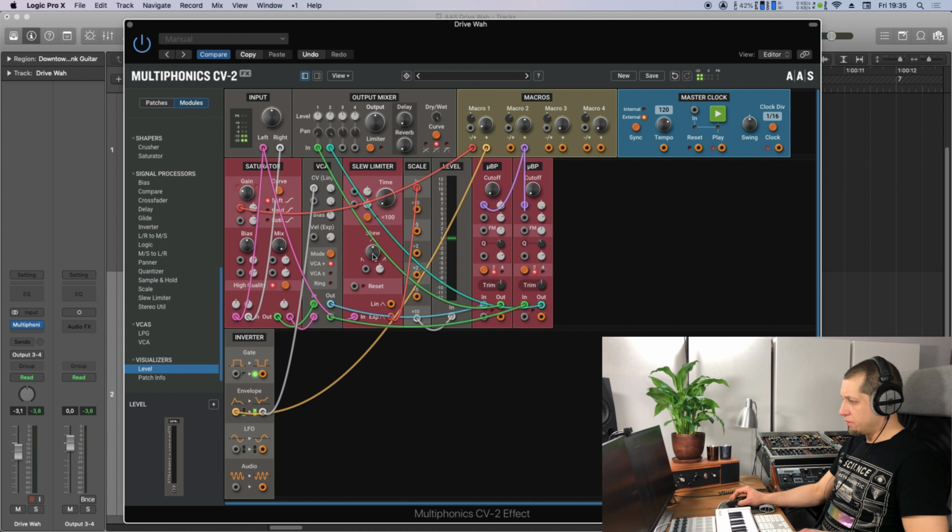You can restrict the rise times and fall times separately with the skew control. For this, I need a fast attack, so the rising edges won't be restricted, but the falling edges will be smoothed out. So the attack of the guitar will open the filter, and then it will close along with the falling edge of the detected envelope.